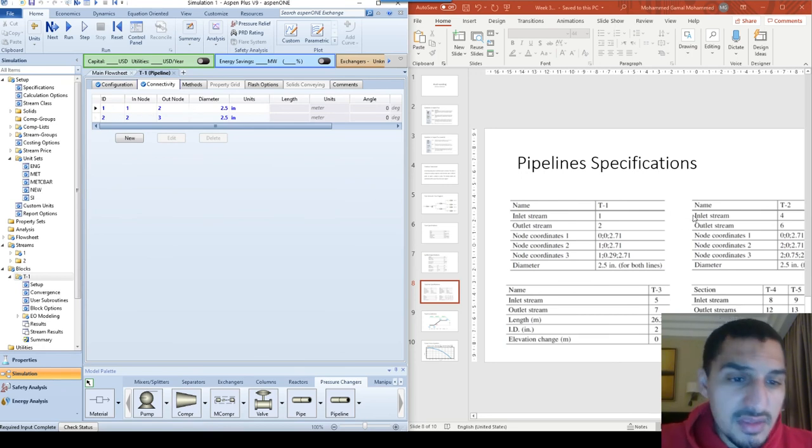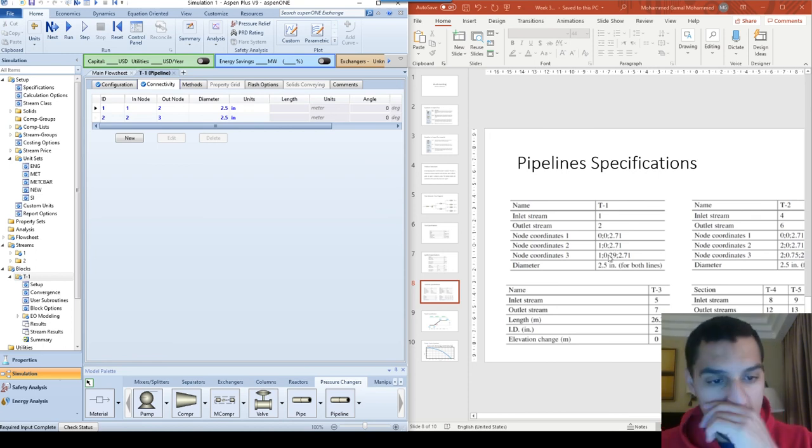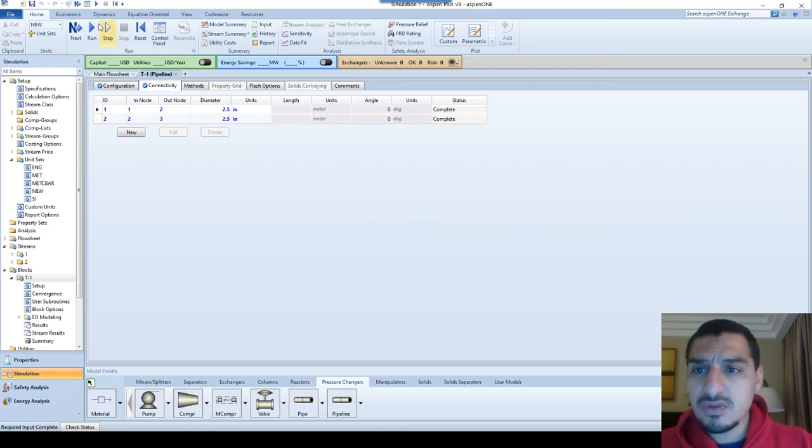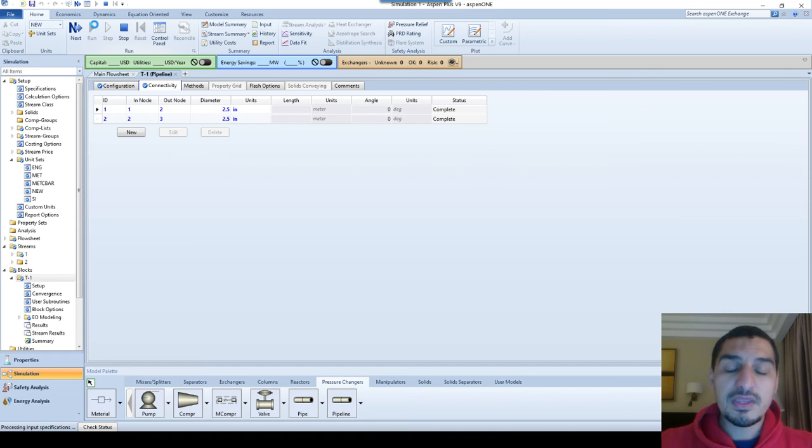So this is all I need to do, just keeping in mind that this is not a very long pipeline. It's just 1 meter and almost 29 centimeters with a change in direction. So I shouldn't expect a lot of pressure losses. So for now we will do the run and just wait and see what the outlet pressure is, and do some analysis of the results and see what we can get out of this.